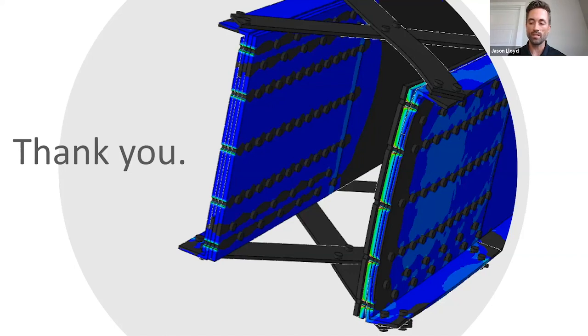We would use the linear elastic fracture mechanics equations to establish what would be a critical length crack. And a lot of those are based on a plate that's floating in space without a lot of the boundary conditions that do exist in built-up construction. And so we realized that they wouldn't be super accurate, but at least it would give us a starting point, right? So we would calculate that critical length, and then we would take the member to that critical load.